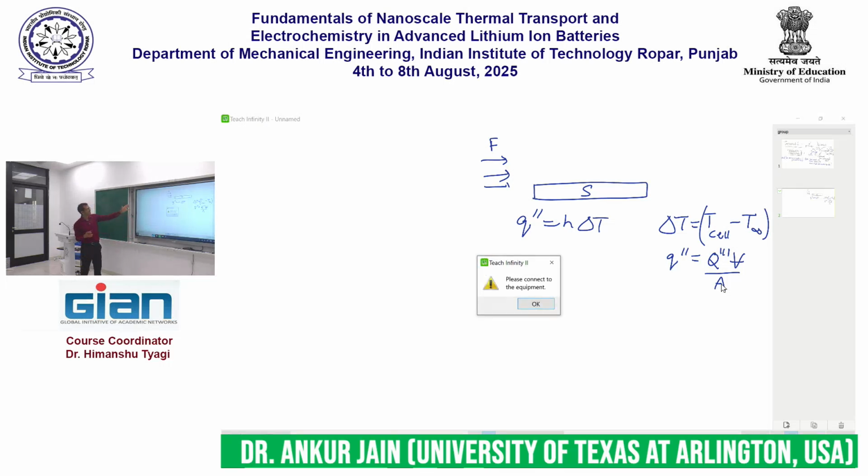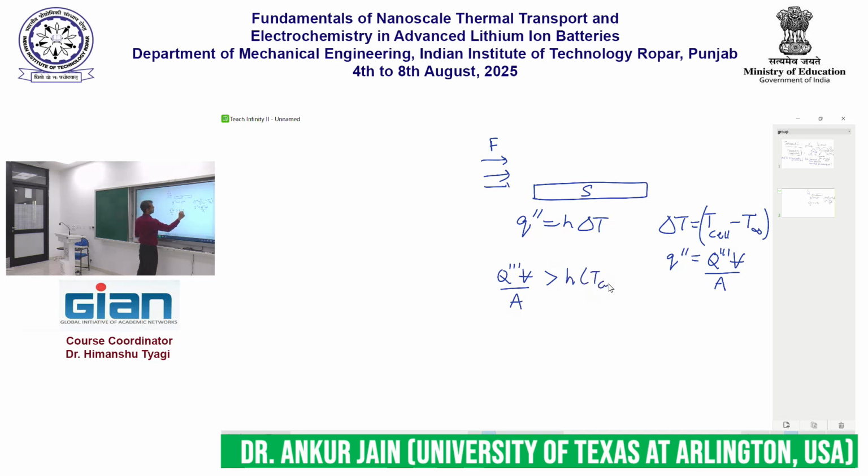Yeah, so you can see that the pieces are coming together. I would like Q triple prime times V over A to be greater than H times T cell minus T infinity. No, sorry, the other way around. The amount of heat that I remove must be greater than the amount of heat that is being generated.